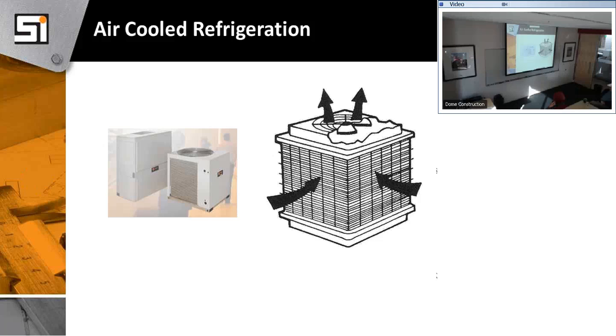What's the definition of a split system? Okay, I may have a slide, but I'll tell you. A split system is where the fan blowing the air into the space is sitting here, and my condenser and my compressor are located somewhere else. A rooftop package unit has the compressor, the condenser, and the supply fan all in one. In a lot of IT rooms, we put a little fan coil in there, and we put the condenser elsewhere, and you see refrigerant piping. That's where we split it. Otherwise, the package unit is all together. No hard questions here.